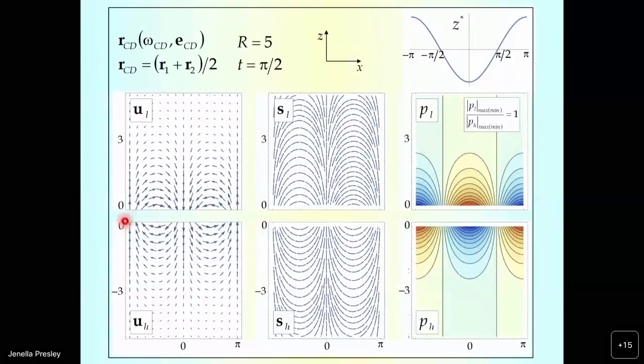The interface is somewhere here, and these pictures were plotted at the time when we did not yet know how to put the theta function in the plot and make it uniform. We have this capability now. But in any case, this is what we have in the light fluid and in the heavy fluid, and it is clearly seen here that the flow field is potential. So the stable dynamics with the stable oscillations is potential in the bulk, no vorticity at all.